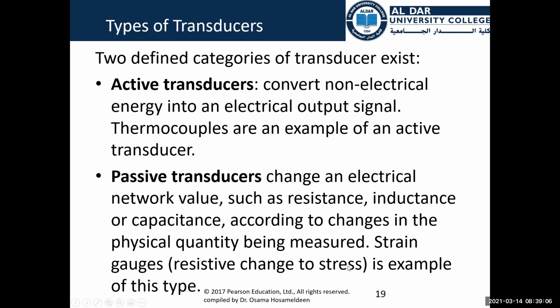So we have stress, and this stress is a physical quantity. We will not convert the physical stress to an electrical signal because it is not an active transducer, it is a passive transducer. It's like changing the value of a resistance. We will see that in this lecture, inshallah. So it's like changing the value of a resistance, not having something in the physical world called stress and then converting that value.